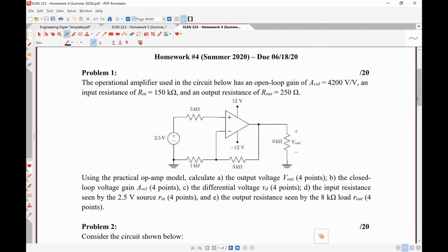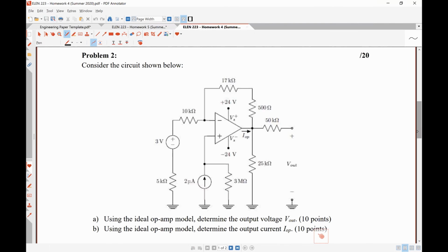Problem 2 as well. I solved it. I'm just not sure. Could you verify this in LTSpice? I'm not asking you to, but is it possible? Because I tried it, and the values were close, but I don't think it was using the ideal op amp. So to make LTSpice use the ideal op amp rules, just change the spice level to 1 in the op amp menu. When you right click on the op amp in LTSpice, it should say something like spice level 2. To make it an ideal op amp, change it to spice level 1.